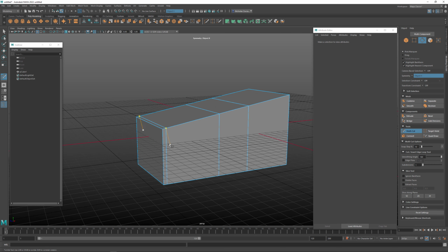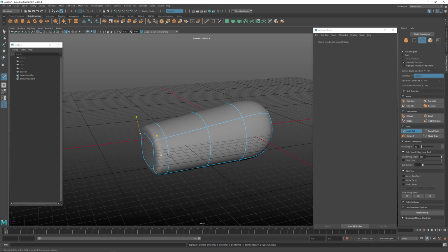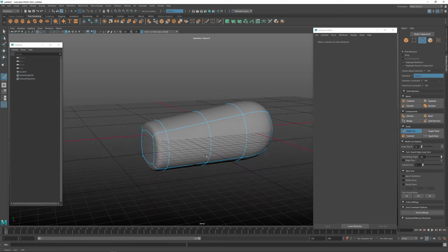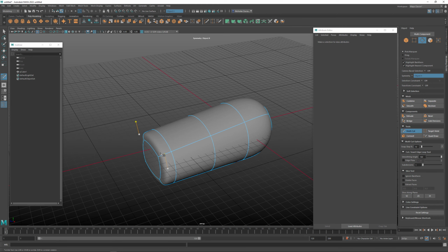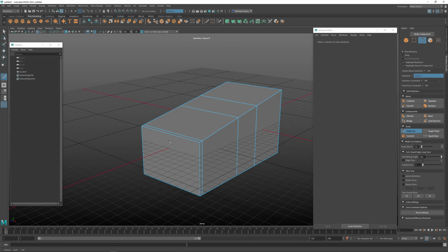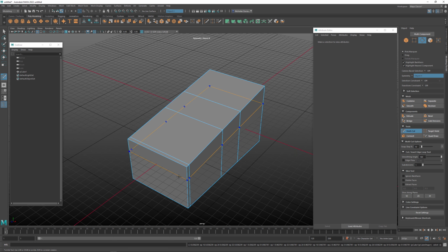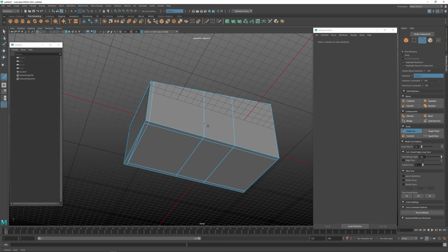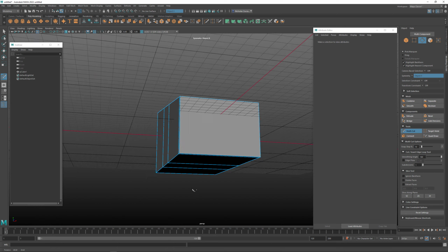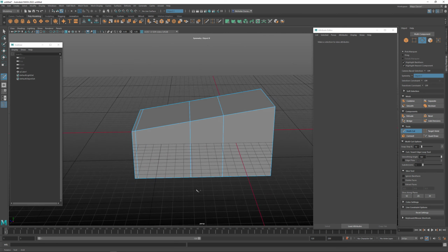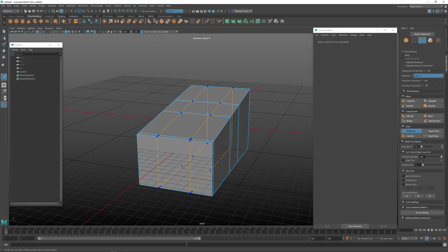we've built what is called a holding edge, or support edge. And if we tap 3, you can see what's going on here. It starts to harden up this edge. Now if I do this on the corners, watch this. If we hold down Control and click here, and I want to hold this edge, and I think I got some bad geometry through here, so let's just click here like this.